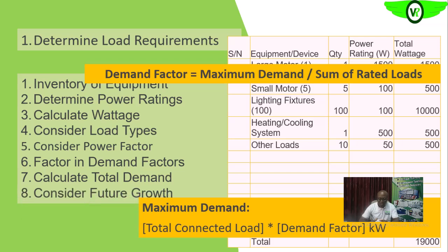Remember too that the possibility of growth will be there. So you need to balance all of these considerations for us to get the right size for our facility. Not that tomorrow a growth that you did not envisage will come, and then the generator will become undersized for your load, and that will now force you or your establishment to want to go and buy another generator. So if you envisage a growth in your load size, you have to factor that in.